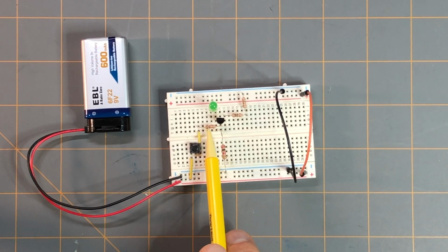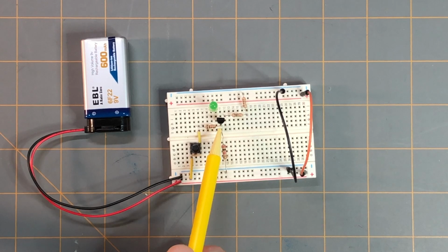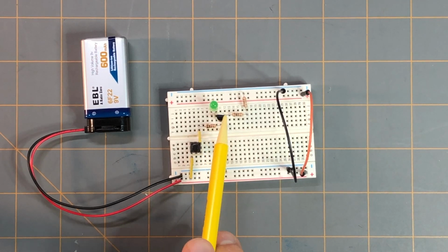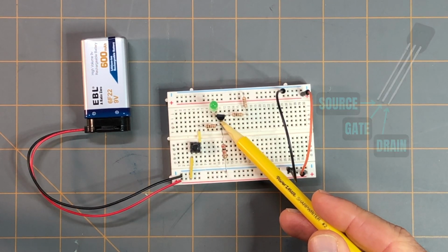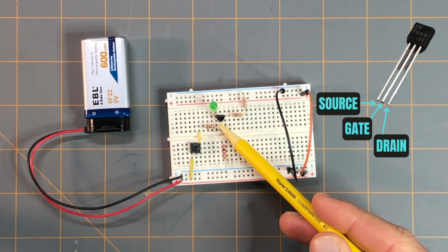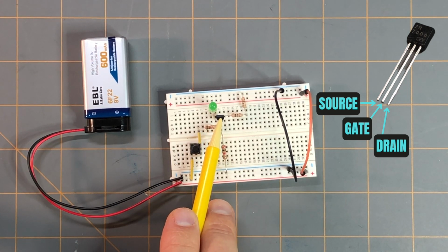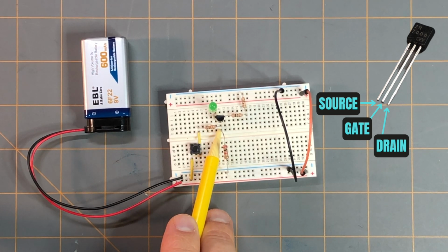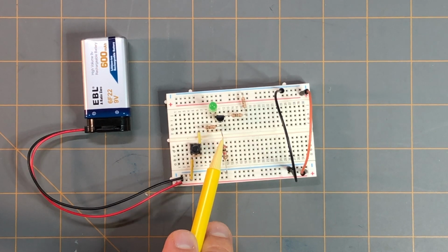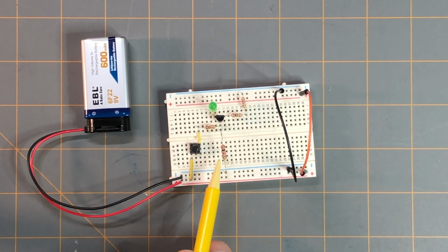This is the 1K ohm resistor, resistor R1, and the other lead of that resistor is in line with the gate of this 2N7000 MOSFET, and the gate lead is the center lead. I know you can't see it from the view that you're at, but the lead to this 1K ohm resistor goes to the center lead of this MOSFET, and that is the gate. Also in line with the gate is the lead of this resistor here, and this resistor represents resistor R2 from that example circuit in the schematic.